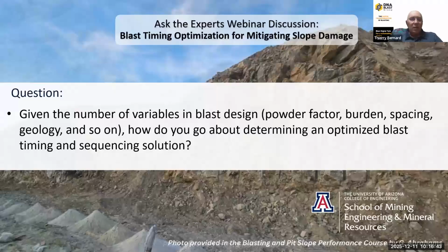Then the timing, if we're looking, for example, for vibration, there are two key parameters. The first one is to be sure you don't have any overlap between charges, so as to be sure you have individual time per hole, not shooting multiple holes at the same time.